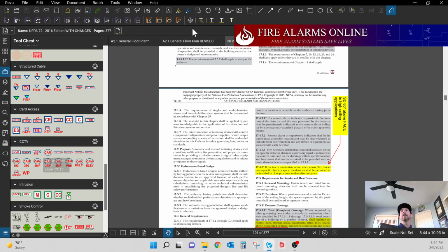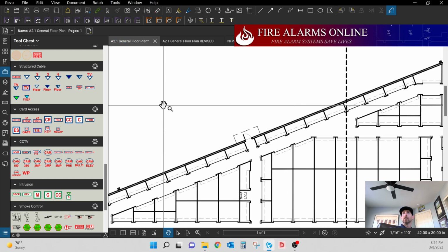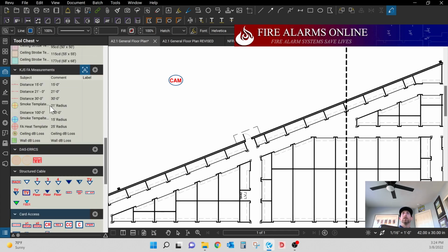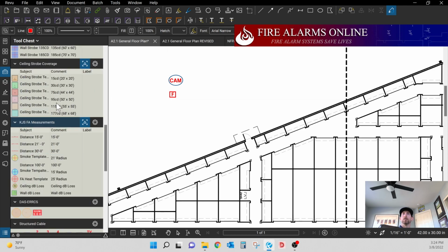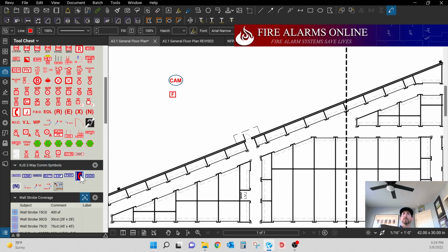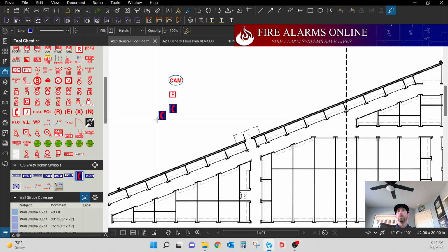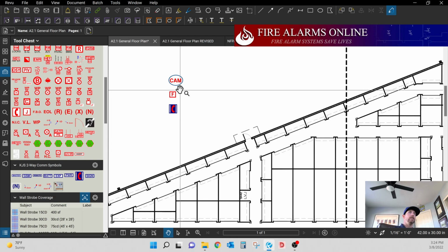The reason I'm telling you that is if you are working in a drawing, I'll just zoom in real quick right here and put a camera down. And I will put, let's see, pole station, and let's go with the phone for two-way. Again, sorry for the glitchy computer. So now we have 3 different scopes on this drawing. We've got cameras on layer CCTV, we've got fire alarm on layer fire alarm, and two-way on the AOR two-way layer.